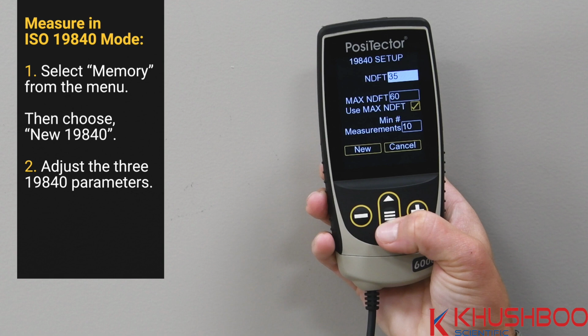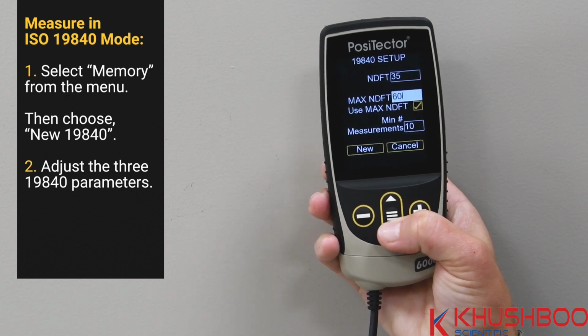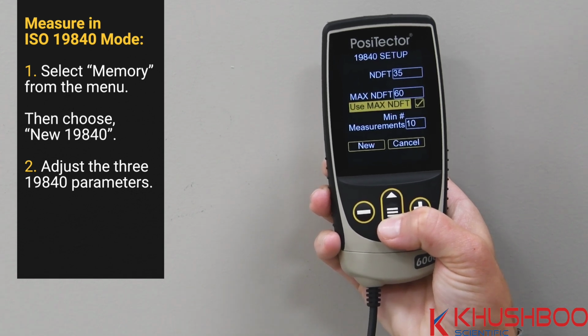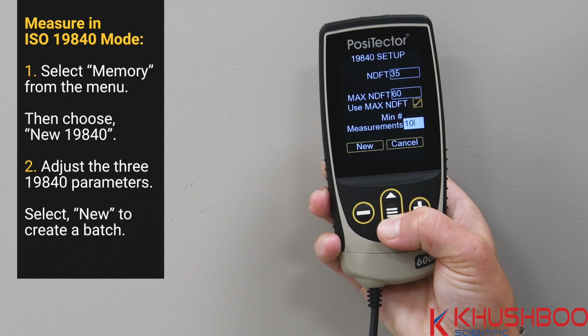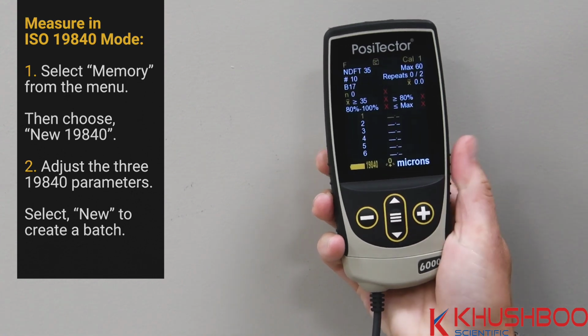Review and adjust the 3 parameters present, including NDFT, max NDFT, and minimum number of measurements according to project specifications. Use the up and down buttons to move the highlighting bar, and the plus or minus buttons to make adjustments to the selected parameter. If a maximum thickness value is not specified, ensure the max NDFT value is set to 0 and uncheck the Use Max NDFT box. Once all of the parameters are set, select New to create the batch.